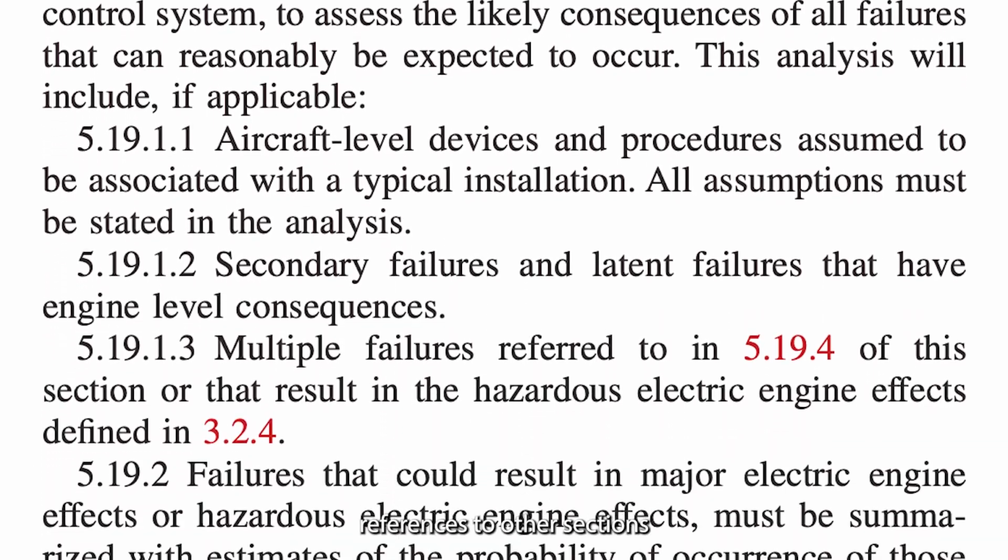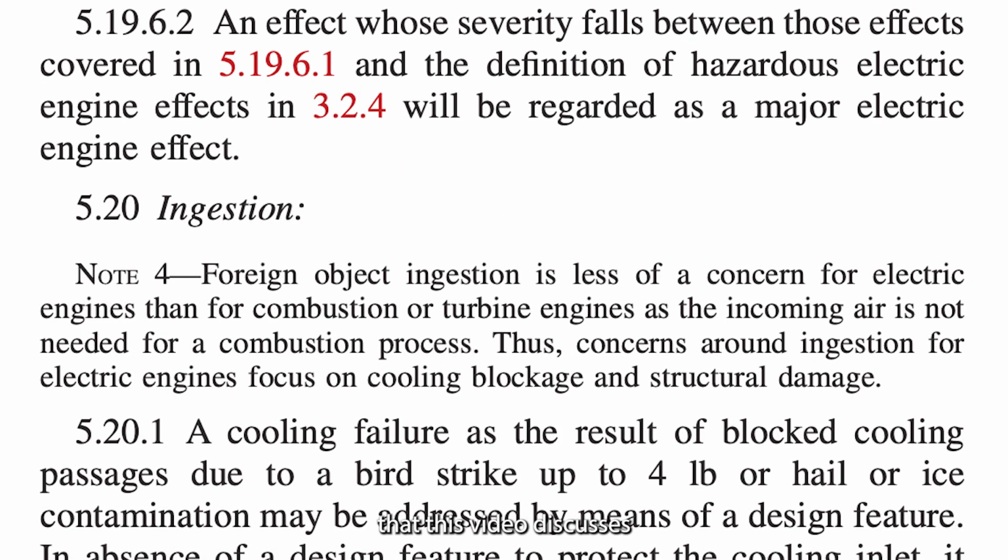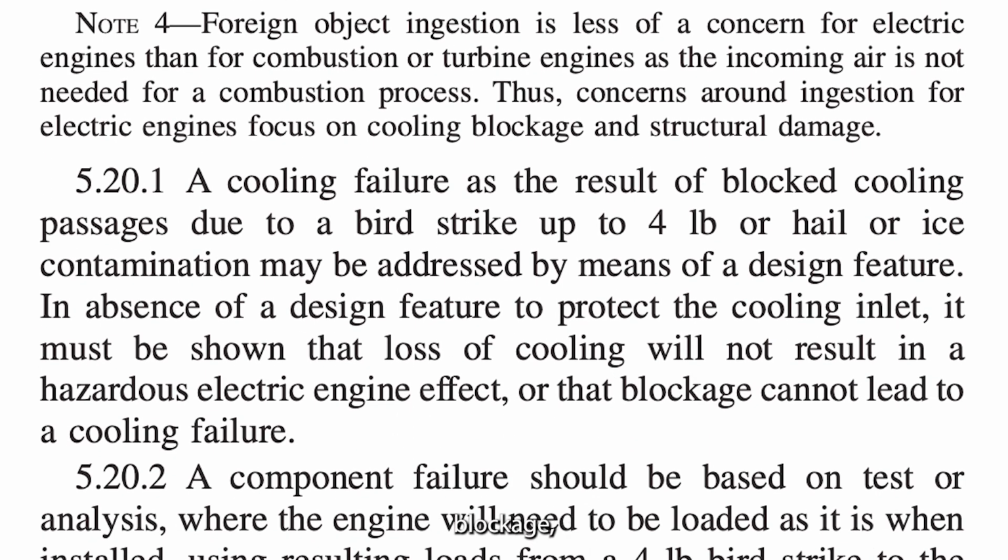This section includes references to other sections of the standard, such as 3.2.4, 5.15, and 5.19.4. The final requirement that this video discusses is Section 5.20, Ingestion. For electric engines, the focus is on cooling blockage and structural damage. Cooling failures are defined as a blockage of the cooling passages due to bird strike, hail, or ice contamination. Any structural damage must not result in any hazardous electric engine effects.